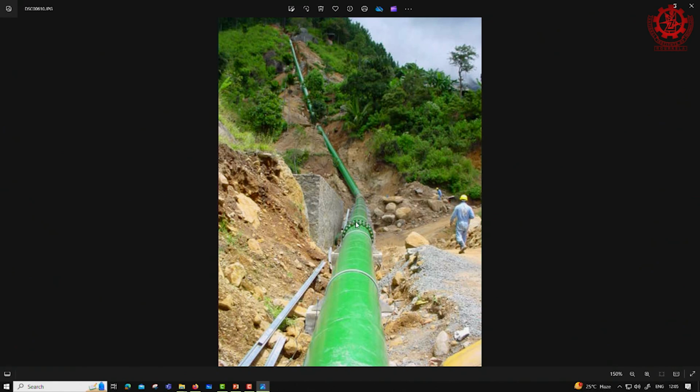That is, someday if we want to inspect this section of the pipe, there is no access. Whether the corrosion is too much after 10-15 years, if you want to access it, you can't come from the top, neither can you come from the bottom, right. So, at the middle point we kept a piece here which can be removed by removing the bolts, and therefore, you can have access and inspect the penstock if required.